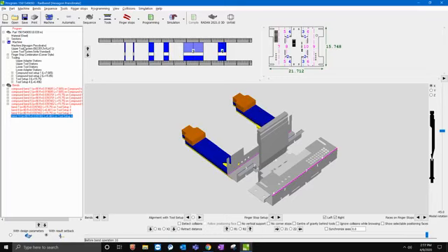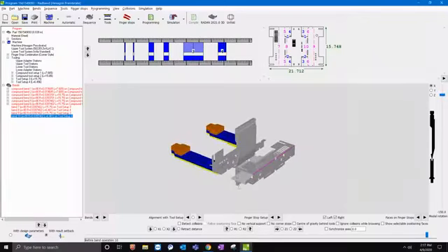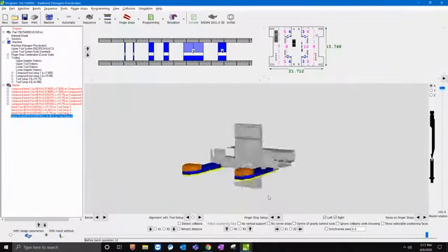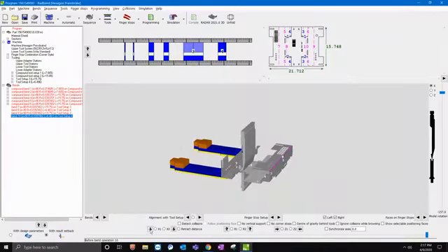So you'll notice that everything here that was red before has turned black, right? And that's because we've done the next step. These bends are black because we've assigned the tool setups, and now we need to just simulate this program and run through it. I can stay in this mode here in the finger stop mode, and I can rotate this model around. I can zoom in, I can take a look and see how it is working, how the fingers are, and you can move them, right? You can move it out and then select this button, hit the arrow, and it snaps it back to wherever I want it to snap to, okay?